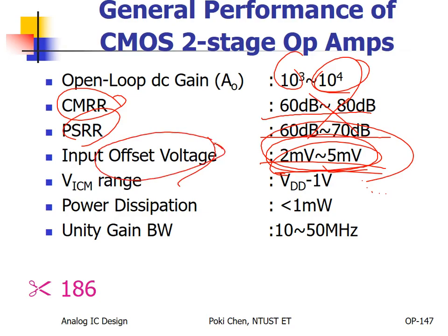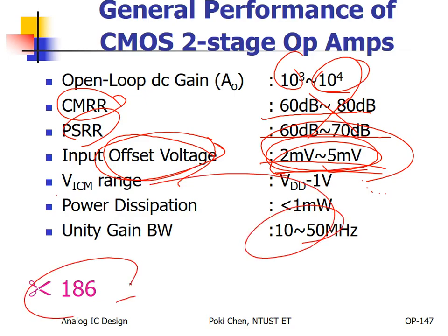To be honest, for high-end applications, the most difficult thing you have to face is input offset. If the gain is not good enough, then we have many kinds of tools, weapons, and skills to enhance your gain. But how about input offset voltage? It's really hard to deal with, especially under high gain application. Wow, the impact will also be enlarged. Okay, just for your reference.